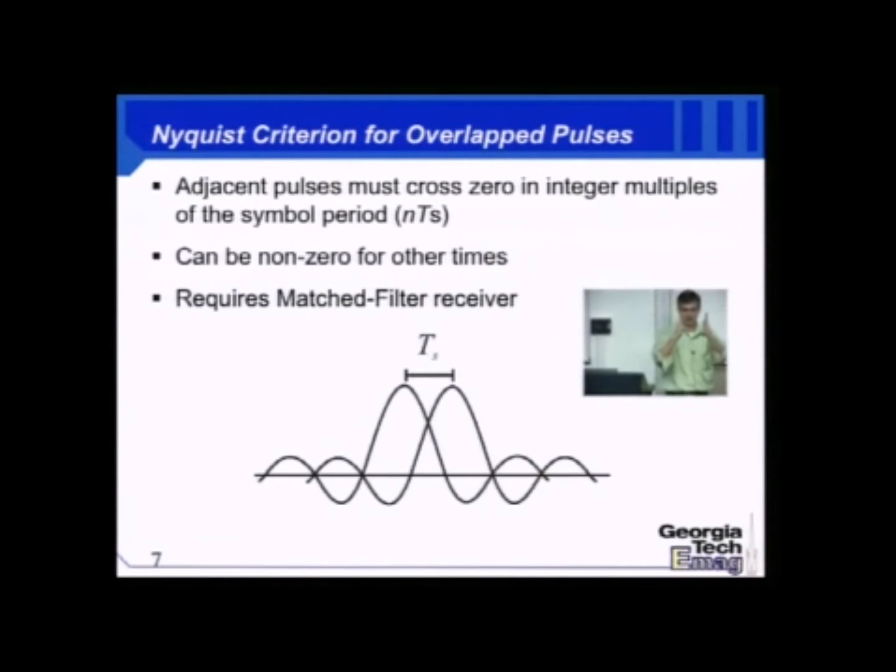Ideally, all of my spectrum would fit exactly in finite limits and nothing else outside. This is a wonderful way to control RF spectrum. Now, there's a fundamental problem. We know that to make a true box in the frequency domain, you need an infinite support pulse. We don't have that kind of time. We're finite creatures, mortal. We can't be generating infinite support time domain pulses to send digital data. And so we're going to have to make some realistic compromises, right? So let's do a little experiment. I have a couple sketches here just to illustrate the trade-offs in pulse shaping.